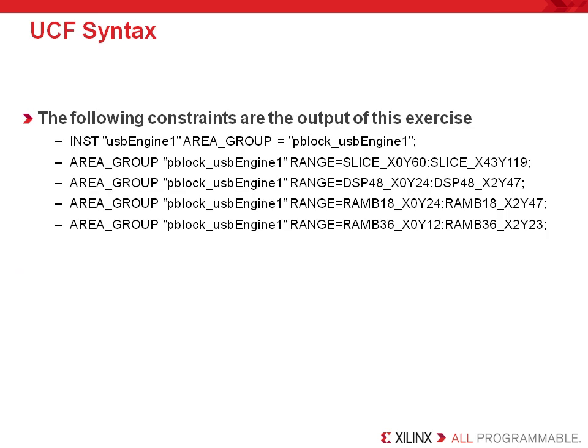PlanAhead creates a construct that enables you to constrain any subset of netlist hierarchy to a region on the chip. They are created using the new Pblock and assign to Pblock commands. The Pblocks are turned into an area group constraint in the UCF to guide implementation, and they keep the levels of hierarchy to various regions on the chip.